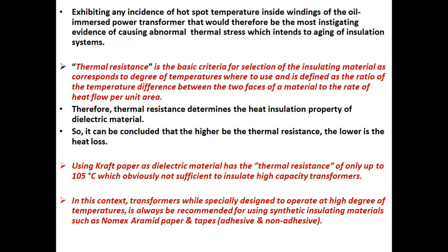Kraft paper as dielectric material has a thermal resistance of only up to 105 degrees centigrade, which is obviously not sufficient to insulate high capacity transformers. In this context, transformers specially designed to operate at high temperatures are always recommended to use synthetic insulating materials such as Nomex Aramid Paper and tapes, adhesive and non-adhesive type.